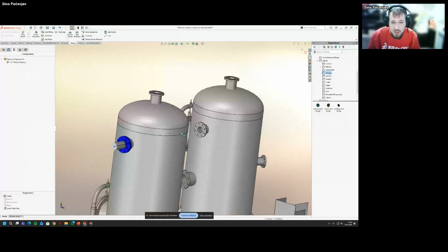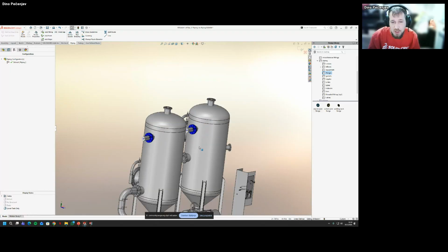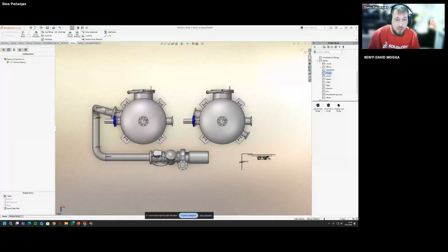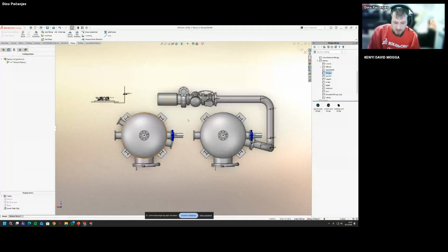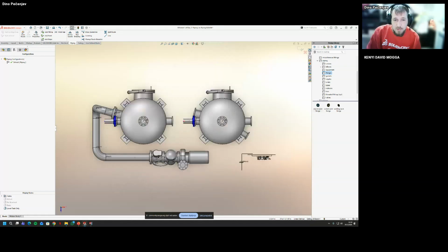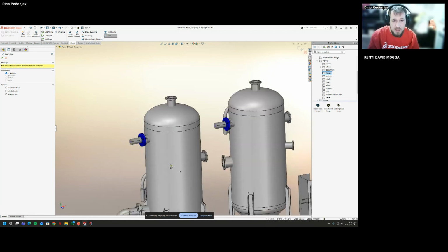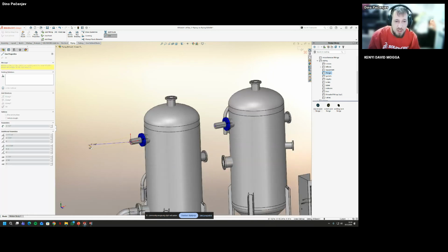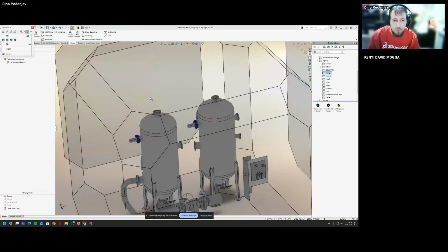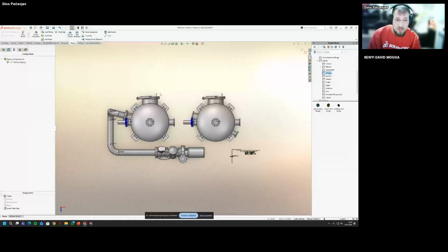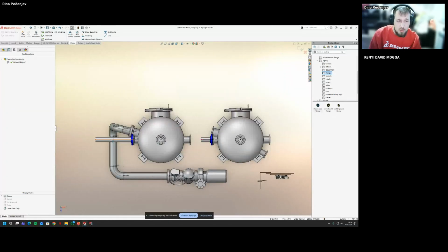And here for the sketching, before I start sketching, I'm adding just another end flange. And one important thing here, I'm just going to reorient here at the top. Just going to switch it. And since we're doing 3D sketching, if you reorient, for example, to the top view, like here, we can just leave it like here. So I'm just going to sketch a simple route.